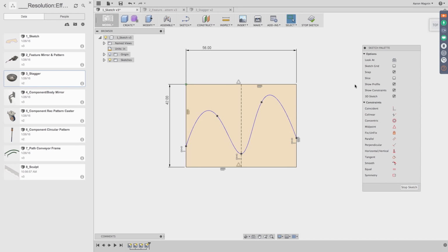So I'm going to double click on the sketch to activate it, and even though it wasn't activated, you were seeing me actually change that spline. That's kind of something that is pretty handy when you've designed something. I'll show you that once I create a feature from this. But to do this symmetry restraint, I'm going to come down here, I'm going to select it, and pre-select it. That's just the workflow that we use in Fusion 360. I'm going to select the one end point, the other end point, and then the last input it's looking for here is the middle plane. So I have this construction line in here. I'm going to select that middle plane, and so these 2 points are symmetric about this line, and you can see there's symmetry dialogues showing that in the graphics area.